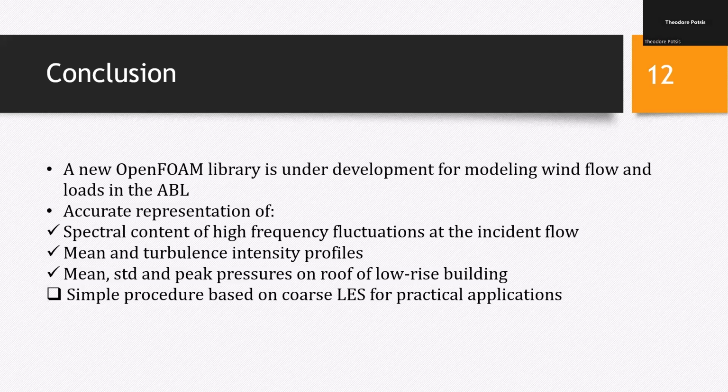And finally, for me, the most important comment to highlight is that this procedure, from our perspective, is a simple one. It's a procedure that does not use the complexity of synthetic inlet, first of all, which is one very important point. And second of all, it's based on coarse large-scale simulations. And this gives the ability actually for practitioners to start using it as a tool. And we're starting the conversation of how basically computational wind engineering can finally be introduced in a very specific way in code provisions and be able to be used for calculating peak pressures on building envelopes.